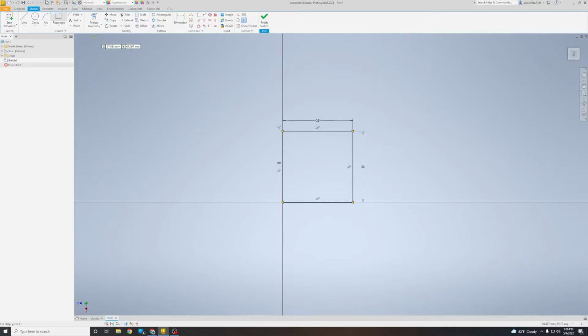If I was designing a little bit differently, I might use my rectangle tool, draw a rectangle down, and then set my dimensions afterwards. This can be done by using the Dimension tool. The Dimension tool is incredibly powerful. It allows us to set the length or the angle or the distance between two lines. It is incredible. I want to set this side to be 25. My first click selects the side, and the second click selects where the label will go.